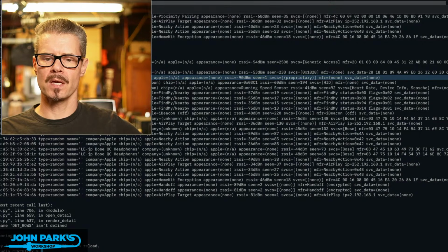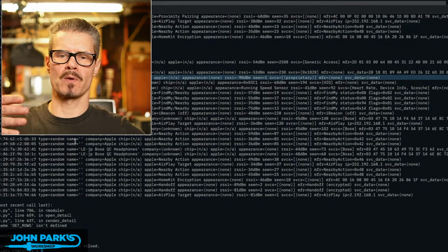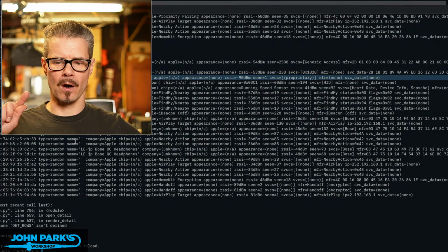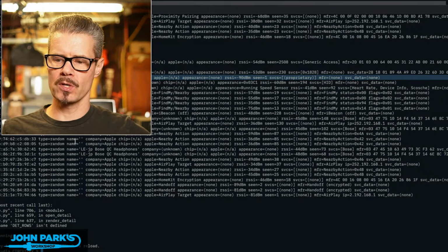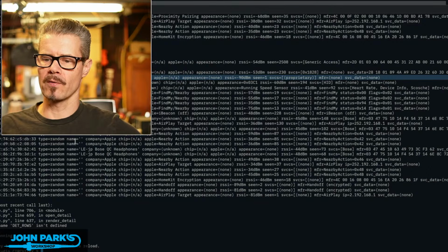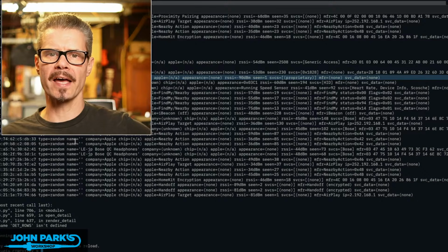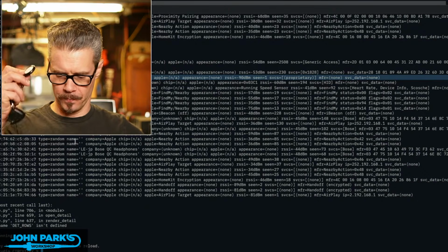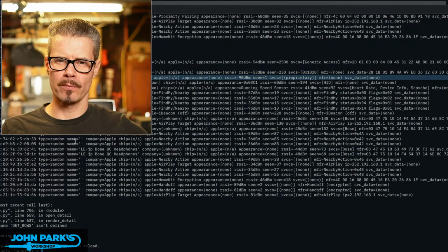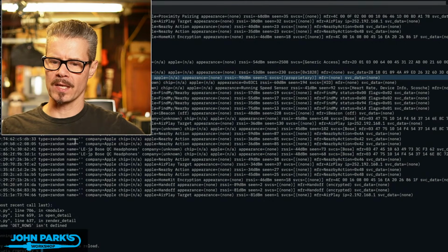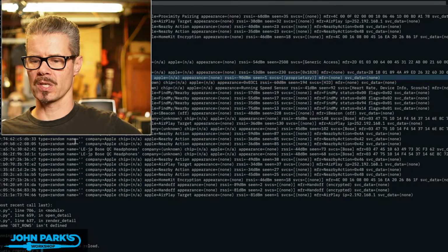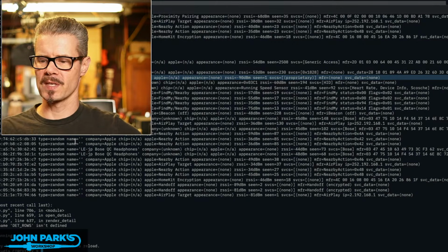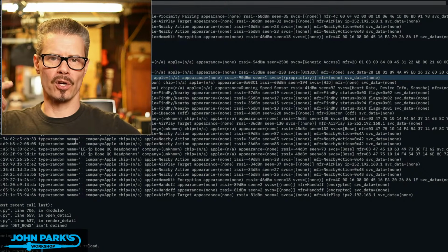But then the random ones, especially if this has been running for a while, you can break into ones that are rolling and changing on a timer versus ones that are only updated when they turn off and on or reset. I believe some security researchers used that as one possible way of differentiating devices. There were security implications with the Tile trackers, similar to AirTags. The Tile trackers had some security vulnerabilities that were not disclosed, and part of it had to do with characterizing a whole bunch of the advertisement data, but noticing whether the scene number was changing, so you could tell if it had updated itself while everything else was the same. You can decide, even though that MAC address changed, I think it's still that one because it's updating on a regular interval.